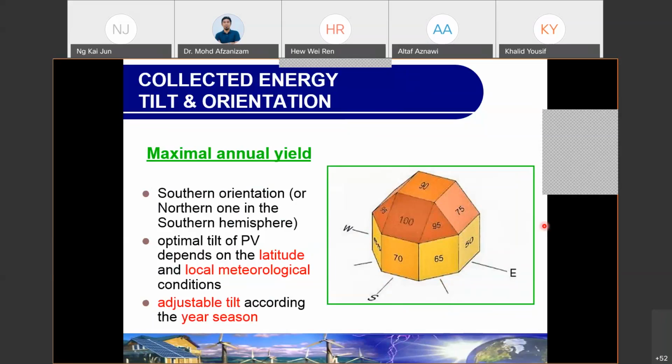It depends on time. Of course, during the morning, just the beginning, and also the afternoon and sundown, it is slightly lower compared to midday. We claim midday from 12 to 2 p.m. So try to capture as much as we can during that time, because before or after that, the sun does not have that high irradiance or intensity, which affects our system.